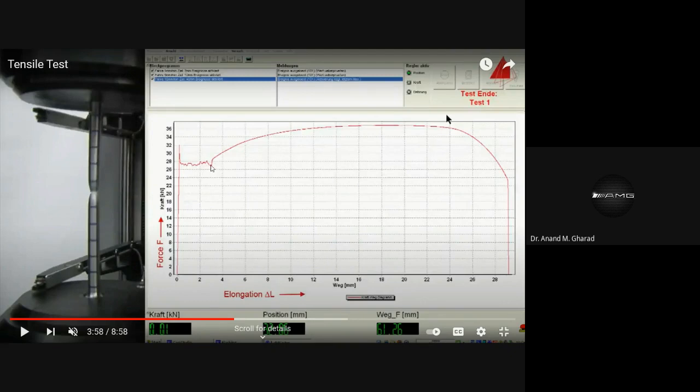Then the point from which the plasticity ends and some nonlinear variation starts, that is known as the strain hardening process. Okay? This is a point where you will observe that the force is maximum, isn't it? This is the maximum force. So if we talk in terms of stress and strain, this point will represent the maximum stress value of that material.